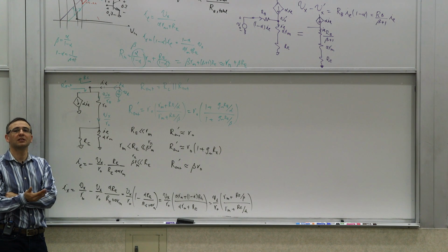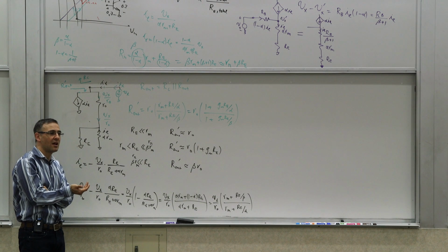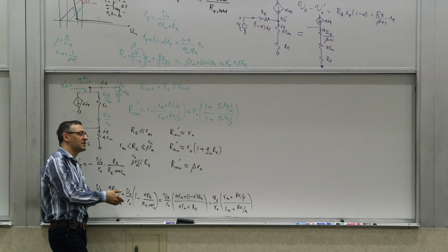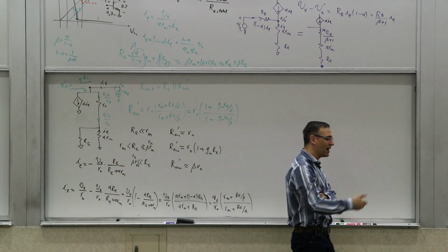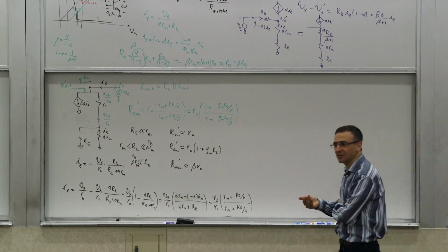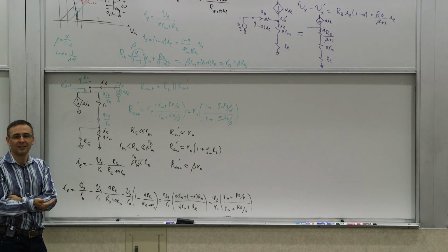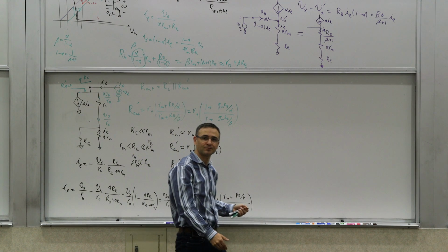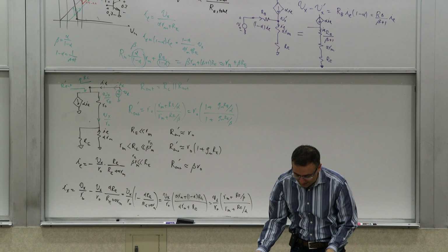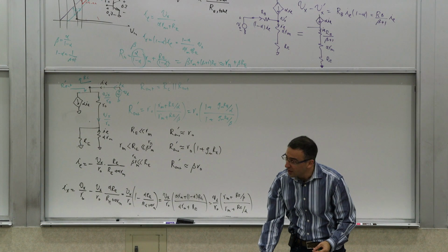And you will see it has topological implications. I'll tell you one example of it. We haven't seen why, but we will see it. The topological implication is that you see double cascodes. You see triple cascodes in MOSFETs, but you don't see them in bipolars often. Because even if you make your resistance infinity in the emitter, it's not going to go above that. So we'll see that. If it didn't make any sense, don't worry about it, because we haven't even told you what a cascode is. Okay, so that's one stage.